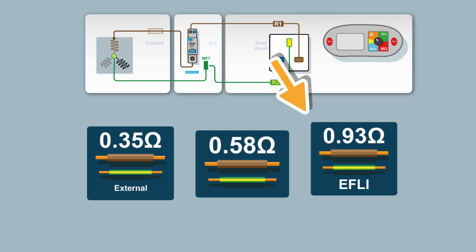It's important to remember that this is a test at 20 degrees C. We're verifying an existing circuit. So we're verifying the resistance is correct for the ambient temperature. If we wanted to verify that these values would be acceptable at maximum operating temperature, we'd have to adjust the values, and then we could see if they're compliant at maximum operating temperature.